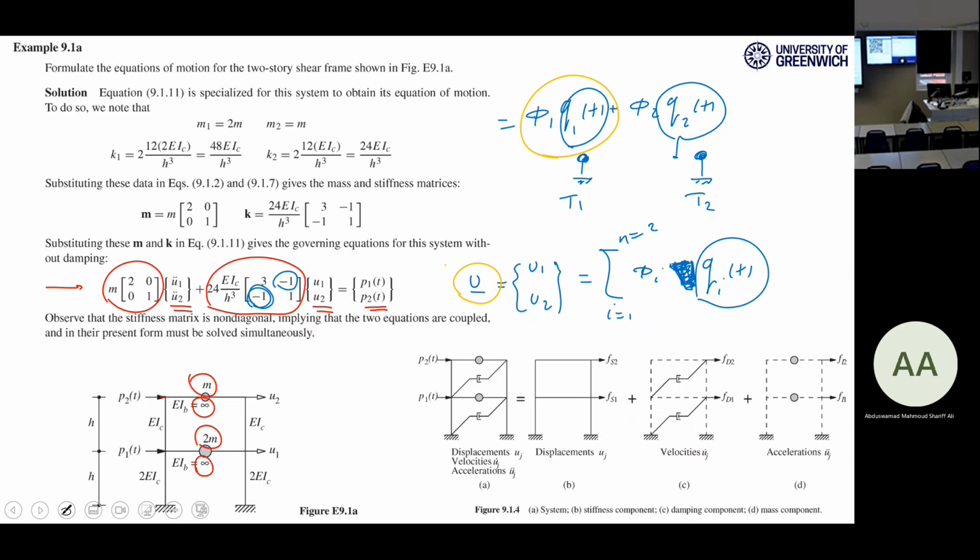And if you have a 10-story building, it's really like this. We have 10 terms, Phi1 Q1, Phi2 Q2, go ahead to Phi10 Q10. In the 10-story building, if you really solve the problem, you will see that 90% of the unknown u relies on Phi1 Q1. I don't know, 5% relies on the second term.